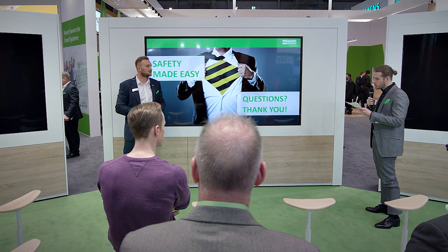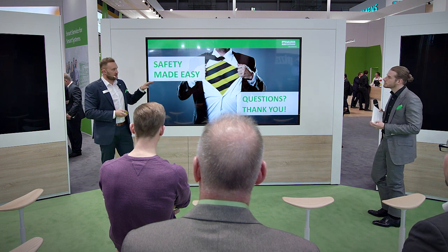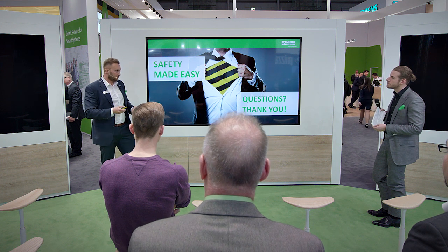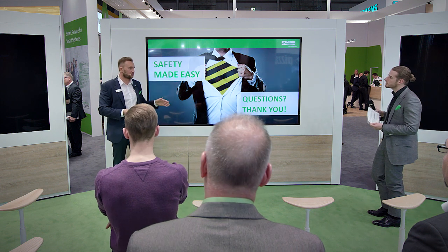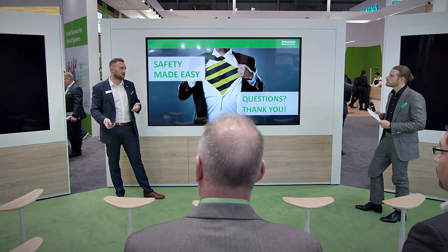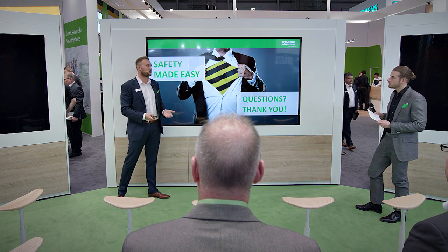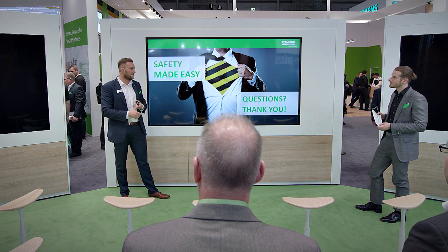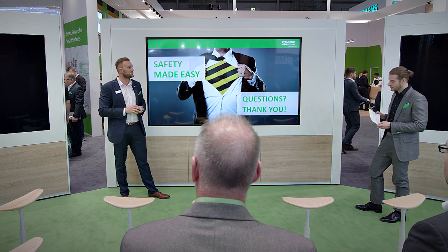Do I need a standard controller and a safety controller? In case you are using a safety controller, it is most often suitable to perform also standard tasks. So if you have a safety controller in your network, it's enough to use it for both standard communication and the safety communication. So you can have your standard components and the safety components in one network if you are using the safety PLC, which saves the effort for the programming, the additional components, and so on, saves time during the installation.